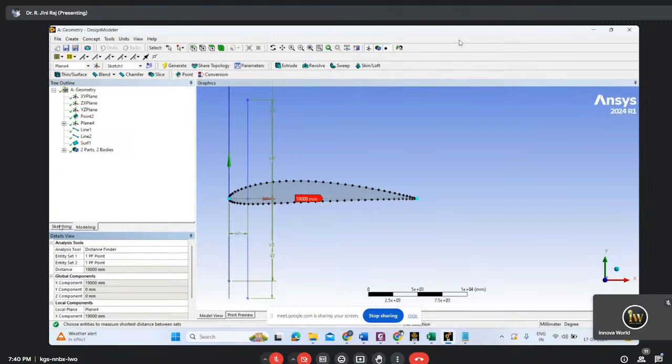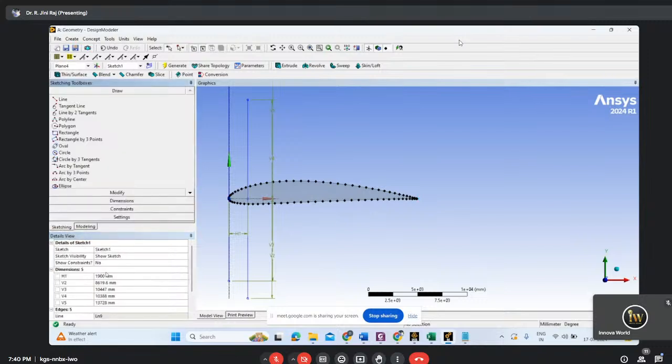So here in dimensions we can provide it should be 10 times. Either you have to scale it down. Now we can do accordingly whatever here. But normally we should scale the total things down to like 1 meter. Below 1 meter will be easy, otherwise it will be very difficult to do some meshing, that's all. So normal chord is like 19,000, so it should be 10 times.